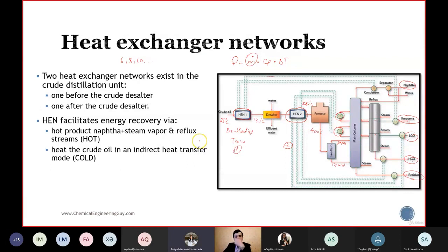And what about how much temperature is recommendable to increase in one heat exchanger in terms of industry? There is no such limitation. The outlet temperature is not what you calculate, it is your result. And for heat exchange network, what is important is heat recovery, the percentage of heat recovery. If you can recover 90%, that is really good.